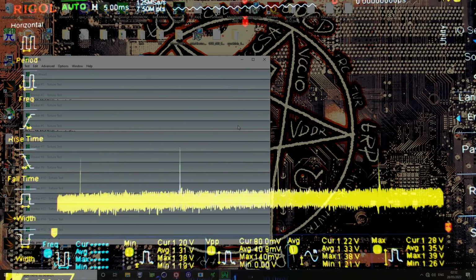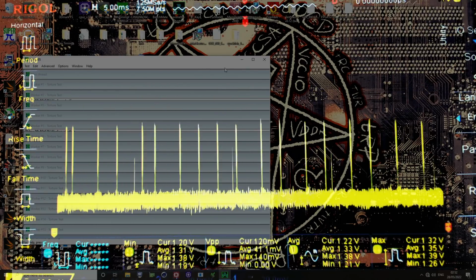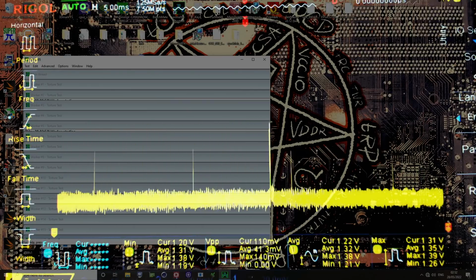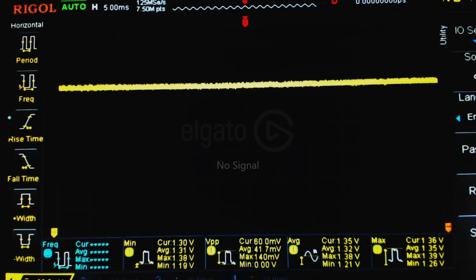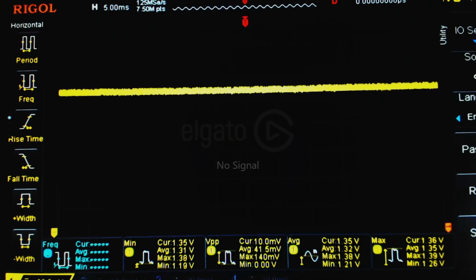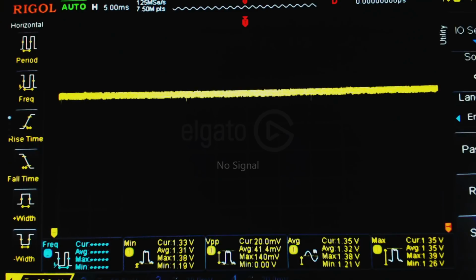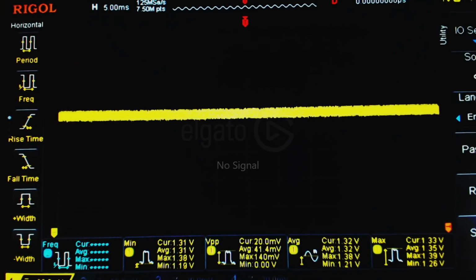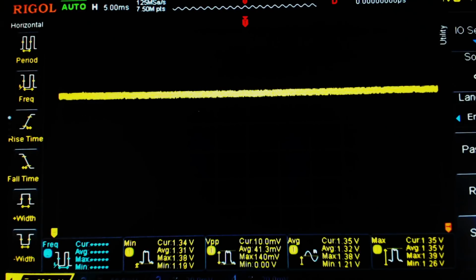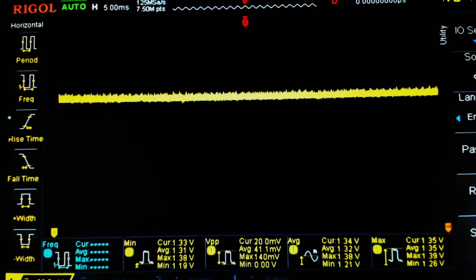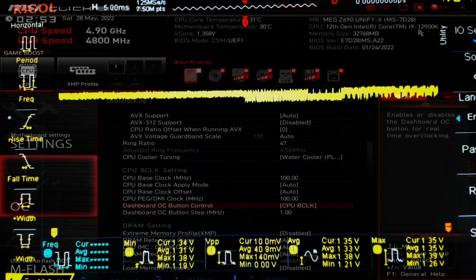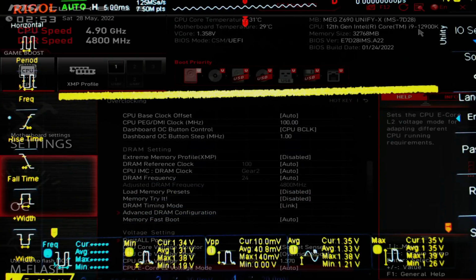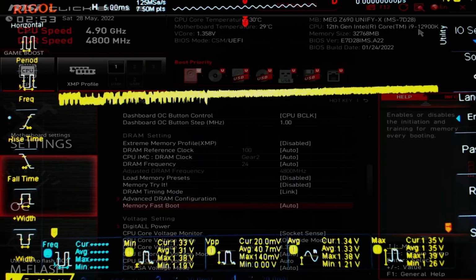Yeah, no, the voltage is actually just 20 millivolts lower if you use socket sense. So we basically have a different amount of V-droop now. Okay, so that is potential. That might have actually shifted around a lot of the LLCs as well. Oh, man. Makes me wonder. I need to check something on the Tachyon after this, I think. Or maybe I'll just ask Gigabyte to tell me what they're doing.